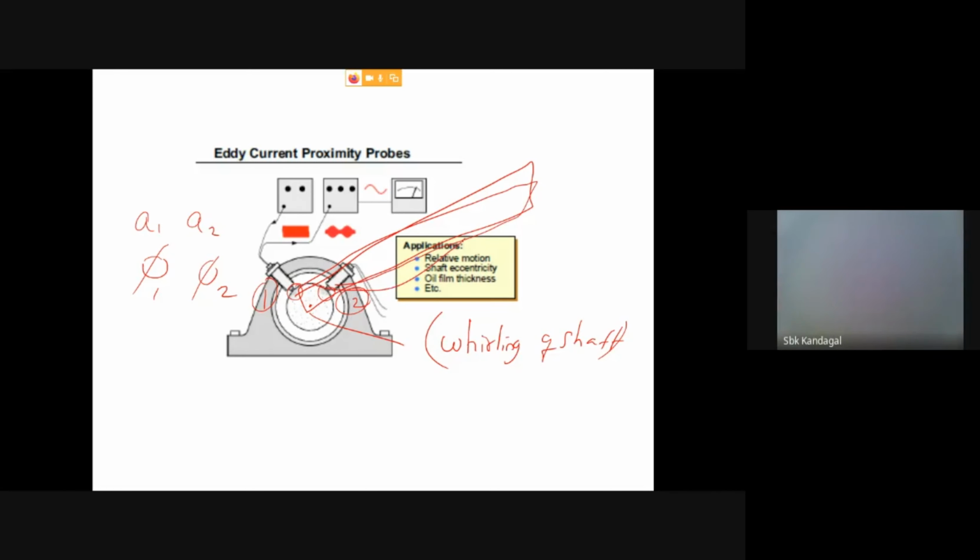So I was telling you about the selection of the accelerometers. Observe here the weight, 0.5 to 0.3 grams. Here the weight is 10 to 50 grams, and still higher ones, as I told you, up to 500 grams. Here the sensitivity is 0.1 to 0.3 picocoulomb per meter per second square. This is 1 to 10 picocoulomb, 10 times to 100 times.